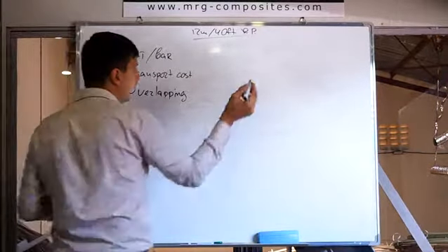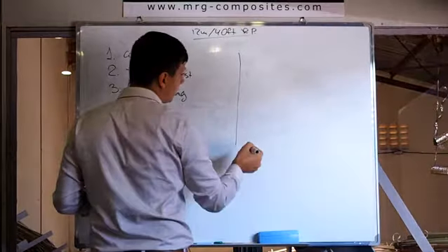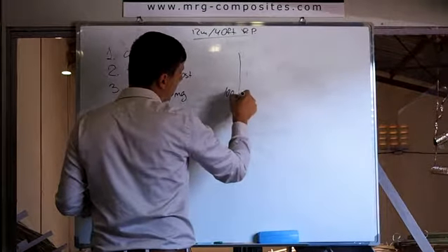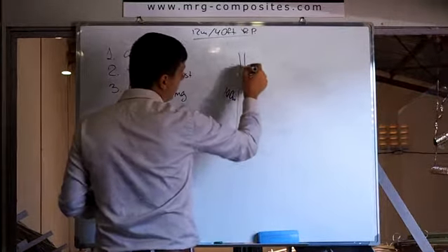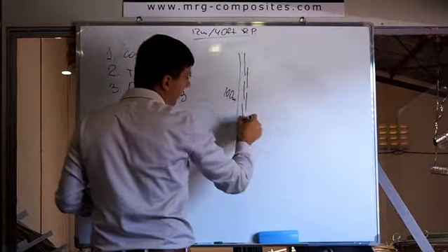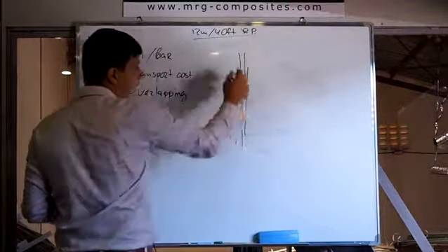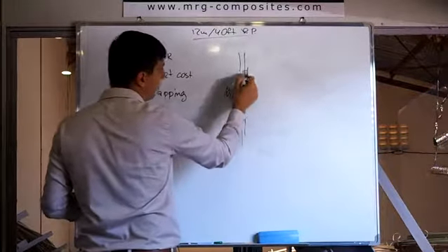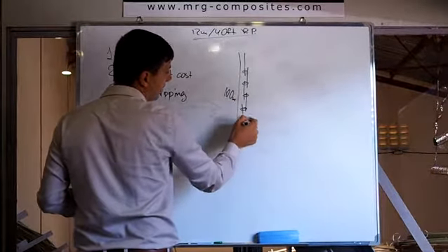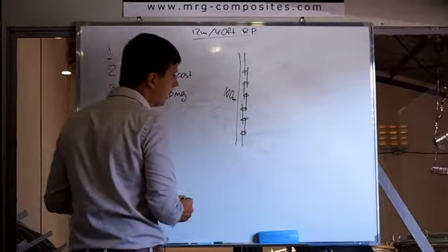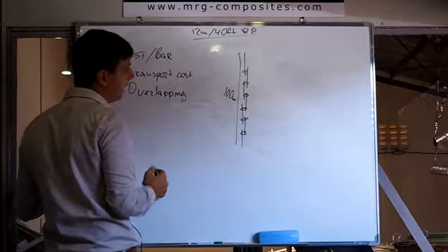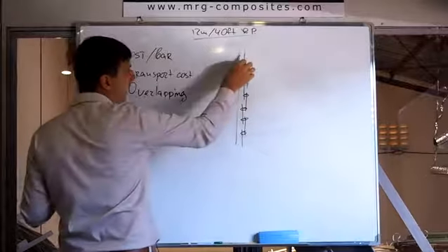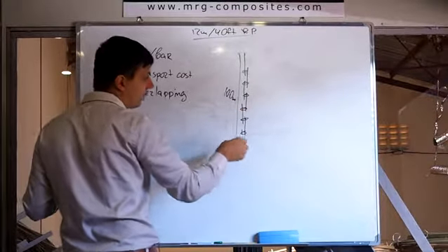Let's say, as I showed before, this is your beam, 100 meters, and you have to use several 12-meter bars just to reach the length. Okay, approximately. This is not the exact quantity, just approximately. And this overlapping is always wasting of your material. So, in case of big structures, we supply in one piece, which can save them.